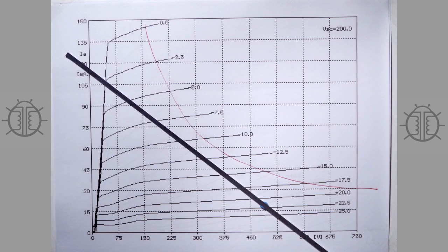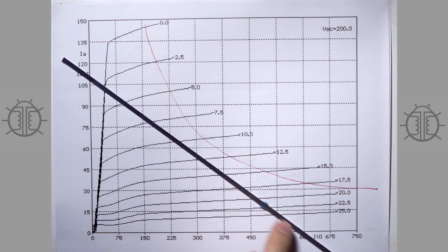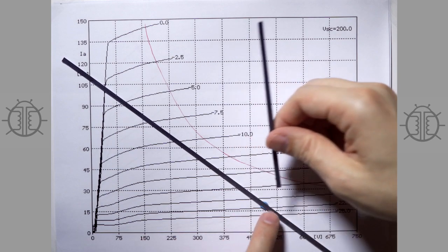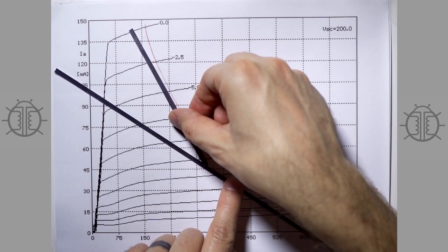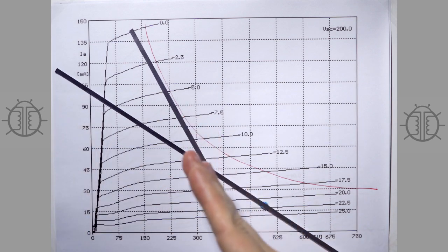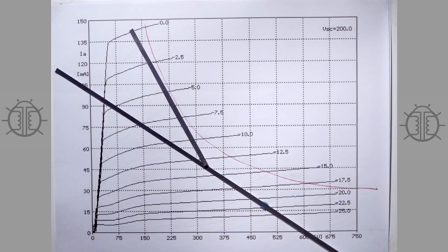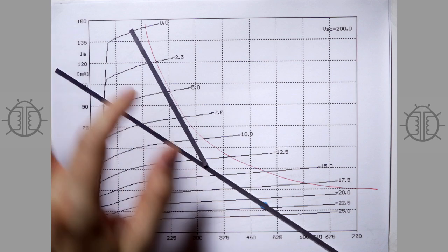And then we know that when we go down a few here, these continue obviously, and you go up a few, we're going to transition to class AB right there. So now we can figure out what our load should be, our plate-to-plate load, and half of that is this guy, and a quarter of that is this guy, just like before. And you can see that we're making more power now because we're swinging more current and we're swinging more voltage.